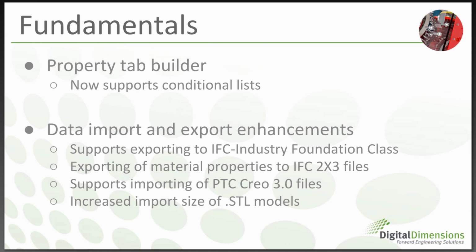And we've also increased the import size of some of these STL models. Now you can import an STL model with up to 500,000 facets, which is a marked increase of 25 times larger than was previously available for solid STL files, and now 5 times larger for surface STL files. So that's another great addition to SOLIDWORKS 2016 this year: the import and export enhancements of some of these files that you might be sharing or bringing in and out from suppliers or sharing within your own workspace.